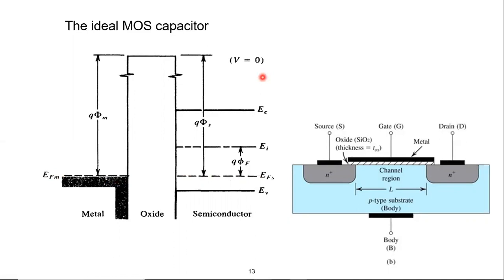Please note two very important notes. First, in the oxide region, we don't have a Fermi level, a conduction band, or a valence band. It's an insulator, or it's a depleted region. No free carrier exists. That's why we just represent this area as an oxide thickness, as you can see, with nothing inside. We are not interested in any energy level here.